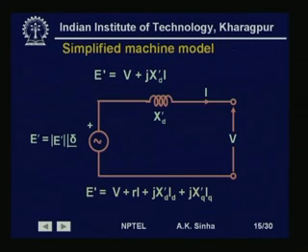Next, we will try to see how we apply this for stability analysis of different systems. Now, here we will start with first using the synchronous machine electrical model. We have already seen earlier that the simplified model for the electrical machine can be seen as a voltage source in series with a reactance, which is the direct axis reactance when we are talking about the cylindrical rotor machine.